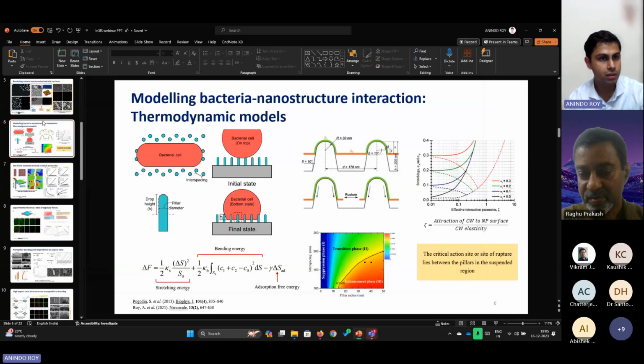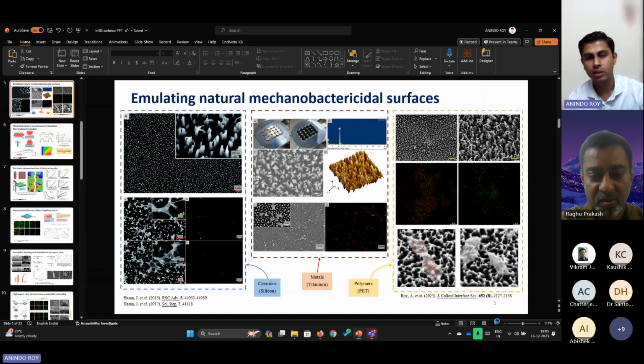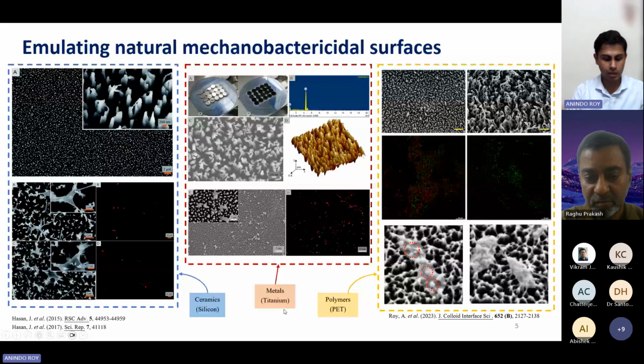So whatever nanostructures you see here, what essentially happens is, let's say in case of SiO2, initially your silicon wafer will have a very thin layer of SiO2. And when the process starts, that will get physically sputtered away. Similarly, in case of titanium as well, it will initially have a thin layer of TiO2. And when the sputtering process starts, it will first get physically sputtered away. That exposes the underlying commercially pure titanium or pure silicon that can then get etched through both chemical processes and physical sputtering. So because the etching progresses in the bulk pure substrate,